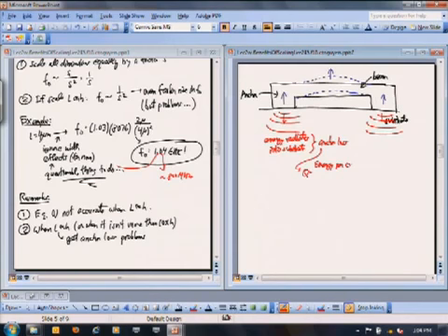So you start with Qs in the order of 8,000, 10,000 or so, you keep shrinking this down. By the time you get to just 100 megahertz or 70 megahertz, your Q has already gone from 8,000 to 300. Okay, it's that steep of a drop-off there. It's still a pretty respectable Q, from on-chip purposes, but not as much as we would like to have to create true revolution in some of these wireless circuits.